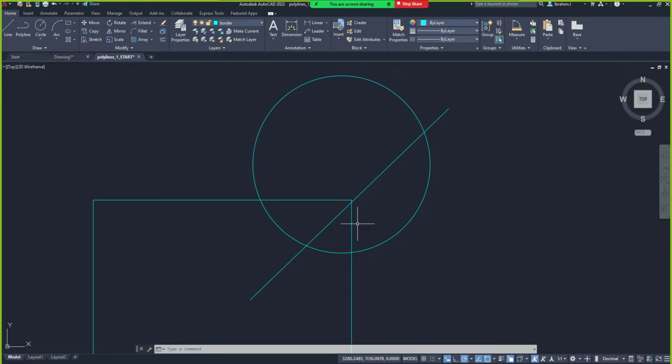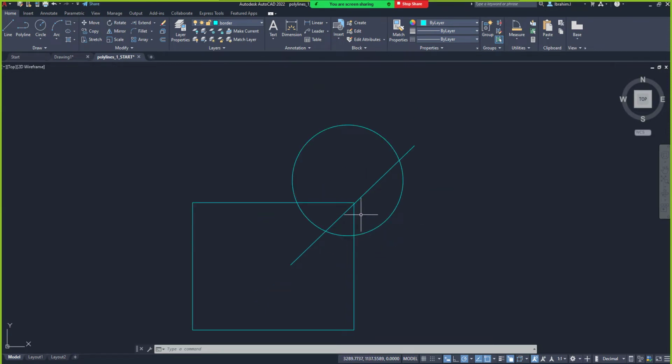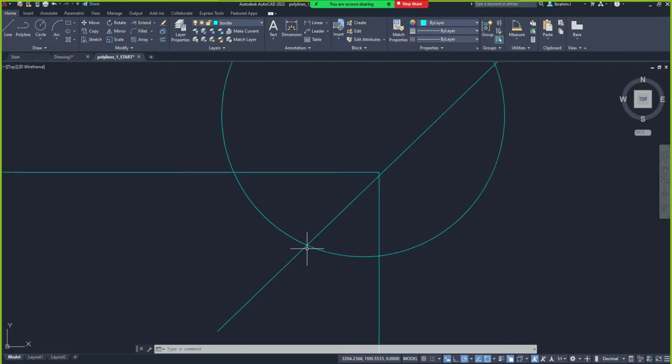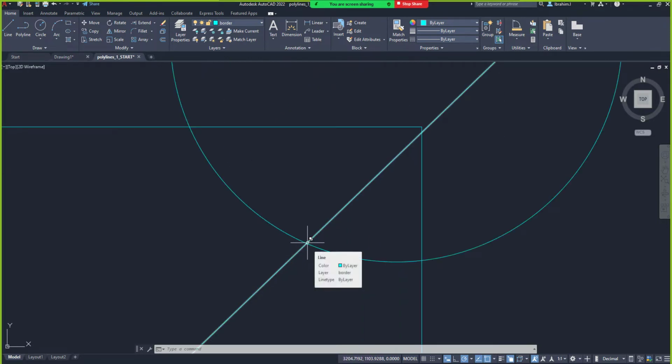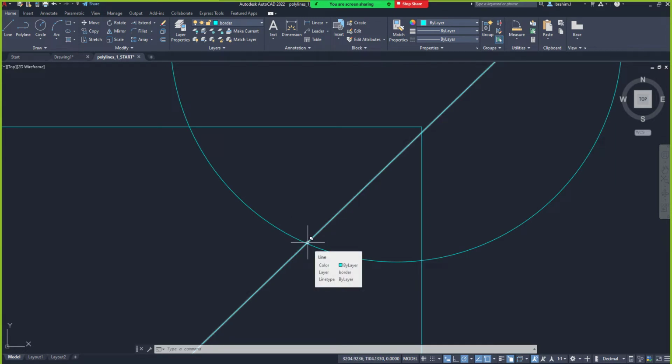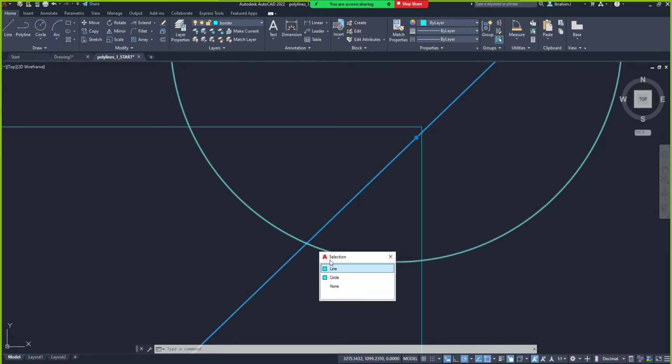You want to select the rectangle that we have below it. Are you with me? For example, I want to select the line and arc, and I'm trying to select it from the intersection. If I'm selecting just the line, it will not give you that icon. Can you see that when I'm on only the circle, you are not seeing that icon? But when I'm on any line that is intersecting, we always have that icon. And whenever you click, it will help you to shuffle them out.